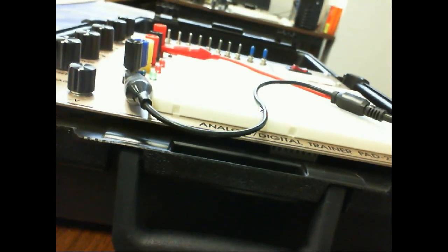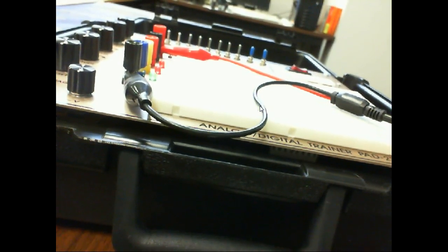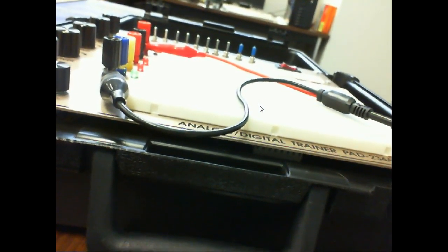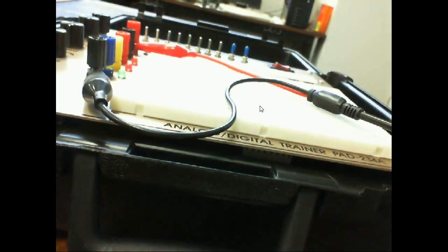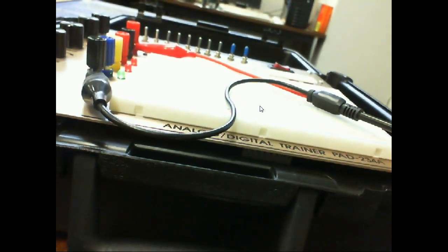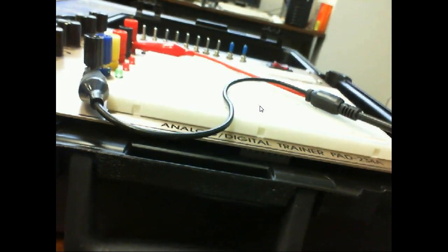But what they'll do is you got a schematic and you're trying to find this integrated circuit. And you got 50 of them on the circuit board. Well, how are you going to find it? Well, they give it a designator, right? And they print that on the board. So they'll have like U3, and you see U3 and you find U3 on the circuit board, and that's the way you can find it.